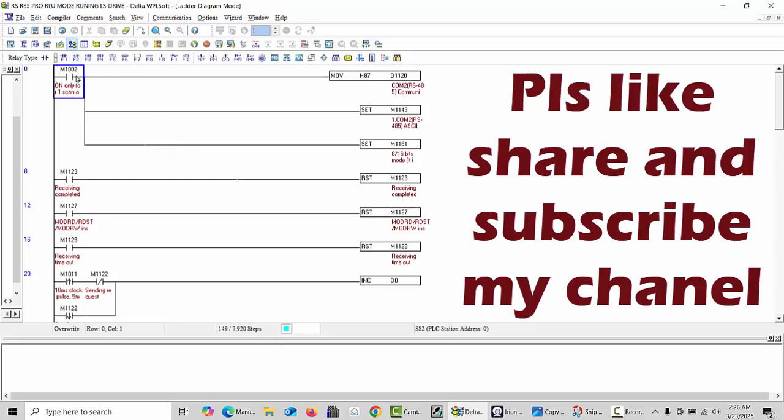This is M1002; you may understand it as the single pulse generator special memory relay. This move command we are using for the communication protocol of the PLC. This is H87 and D1120, the special address we have to set, which matches what we set in the VFD.